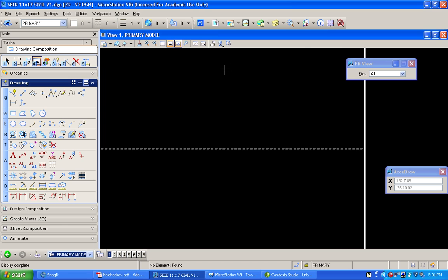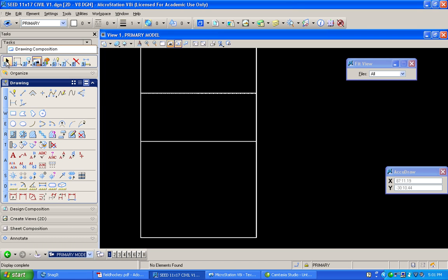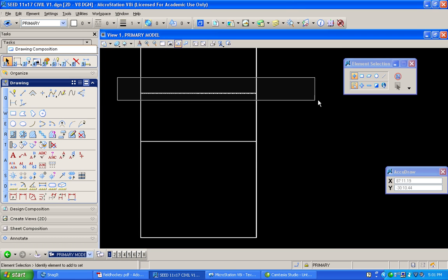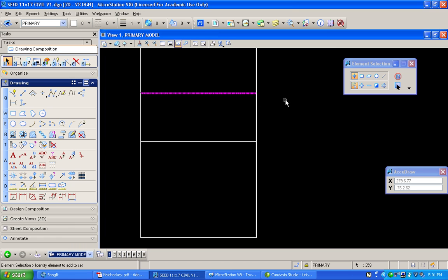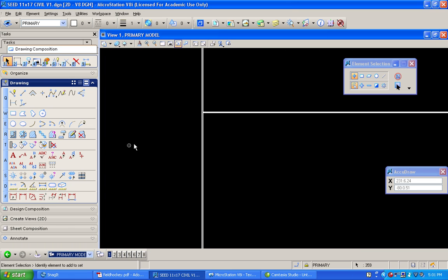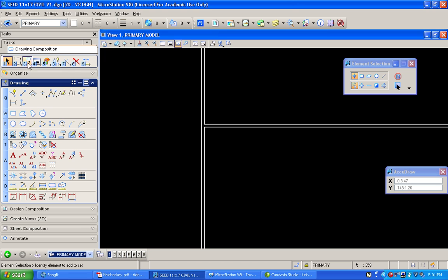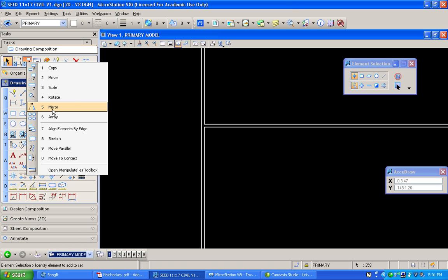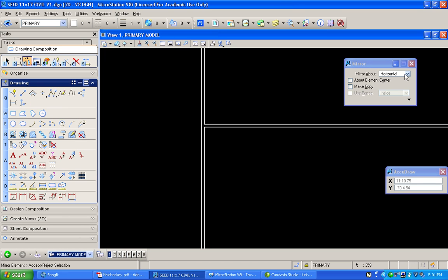And see how I can find this center point on this left line? Just left click there and then right click. What you'll find then is it actually duplicates that on a horizontal axis to the bottom half, and that's really all you need. So we just unselect it, and then we just have to come back to 7-2 partial delete and retrim it out.